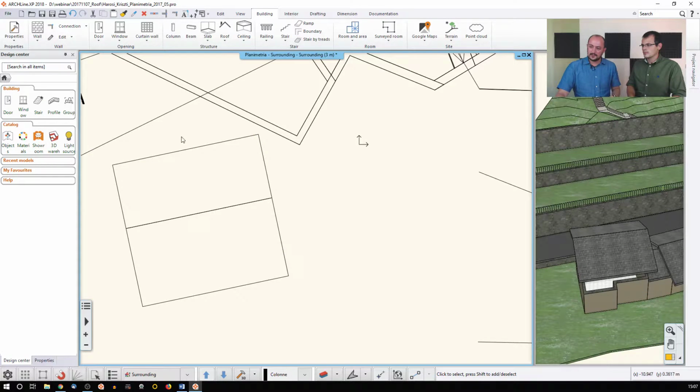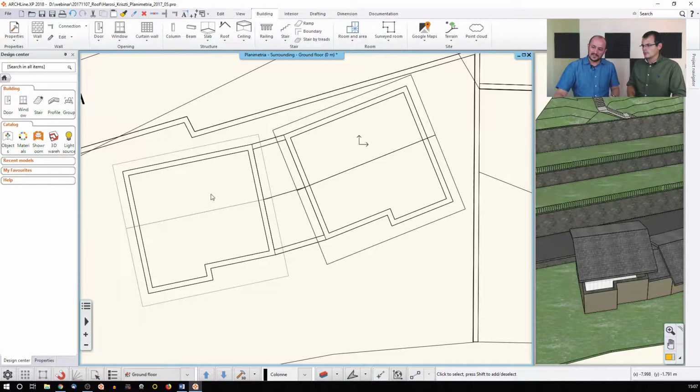And in this case, you will see a clear roof structure on the one floor above, and there is a faint roof structure and the most important parts, the walls. But this comes with a disadvantage, because by default, when you move things from one floor to another, they inherit their 3D position, of course. So you would need to compensate, as it is always measured from the zero of the current floor. So if you move something one floor above, it will be shifted in the 3D. So you suggest that we compensate for that, push it downwards? That's the only thing you need to do.